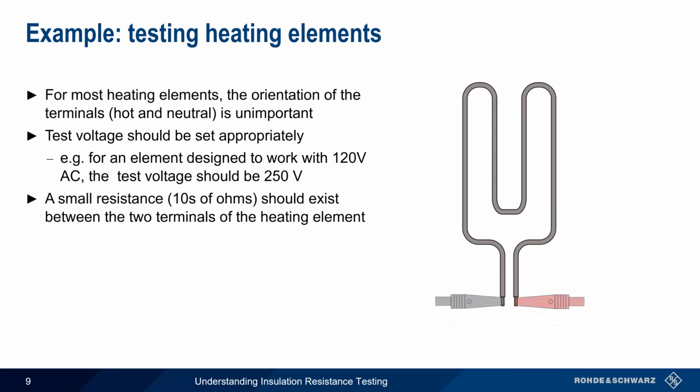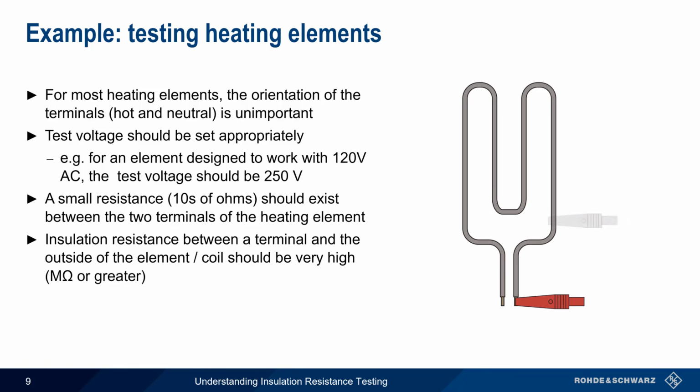If we first measure between the 2 terminals, we should see a small resistance, maybe tens of ohms. But the resistance between a terminal and the outside of the element or coil should be very high, megohms or greater, when tested using an insulation resistance tester.